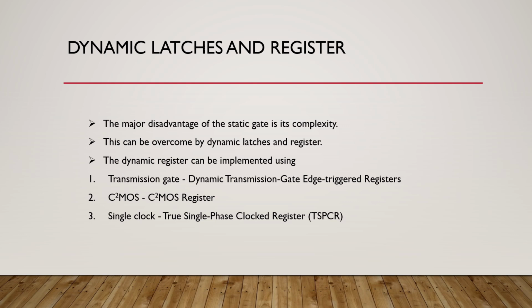If you want to design the master-slave static latch and register, it requires 20 transistors in total, whereas dynamic latches and registers require far fewer transistors. That's what we are going for here.